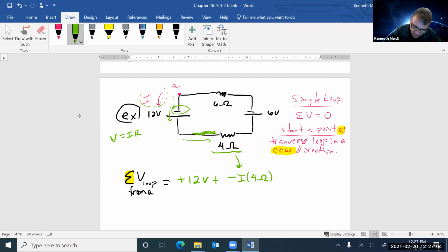Well, where did that come from? Well, that's just this right here, V equals IR. This is voltages around the loop, and I'm just looking at going in a single direction. It makes no difference which direction you're going in, but you have to know, am I going from high energy to low energy or low energy to high energy? That's what you really want to do here, because right here the charges have really high energy, and when they go across, they meet some resistance, and now they've got lower energy. So they reduce their energy, and that lower energy is this minus sign.